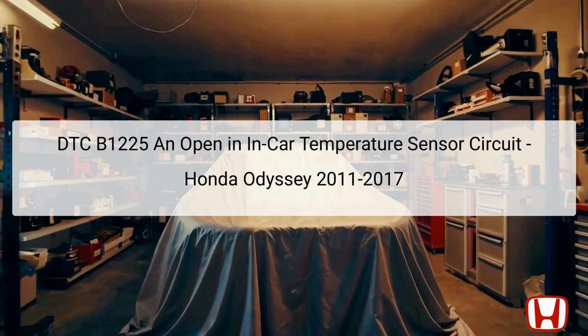For the Honda Odyssey models from 2011 to 2017, the diagnostic trouble code B1225 indicates an open circuit in the in-car temperature sensor. This code is crucial because it affects the vehicle's climate control system, which is responsible for maintaining the comfort of drivers and passengers by regulating cabin temperature.